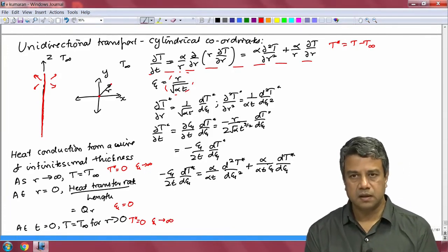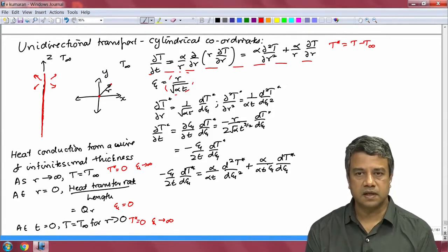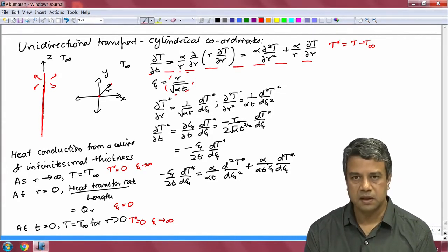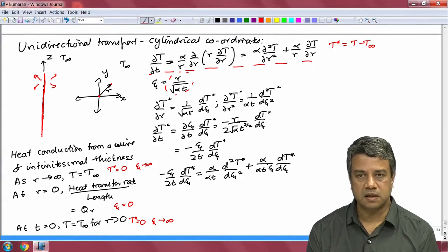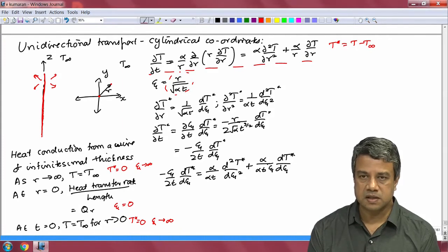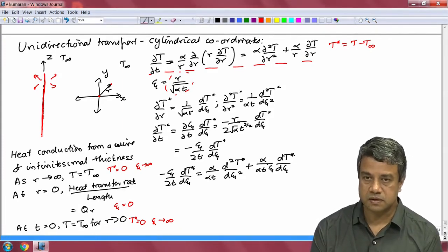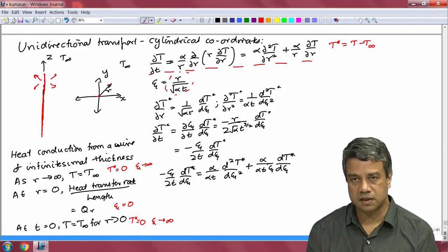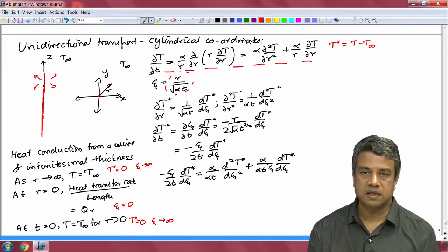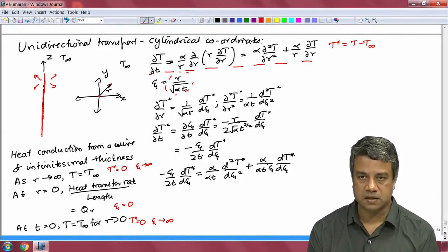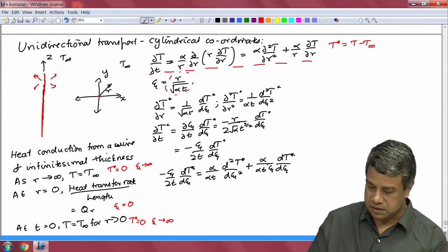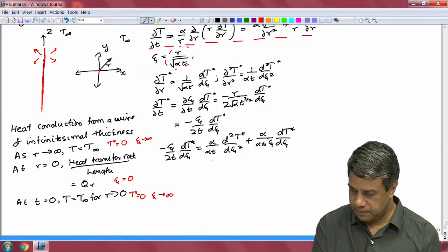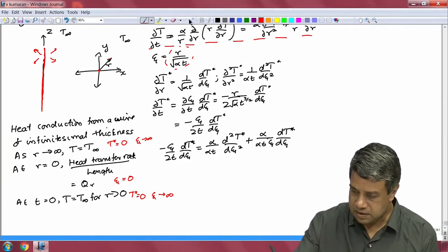Okay. So, recall that in the case of heat transfer in one dimension as well, we had two boundary conditions and one initial condition, and when we expressed the boundary and initial conditions in terms of the similarity variable, one of the boundary conditions as z goes to infinity was the same as the initial condition at t is equal to 0. So, in the transformed coordinates we had only two independent boundary conditions. The same situation applies in this case. Okay, you have only two independent boundary conditions.